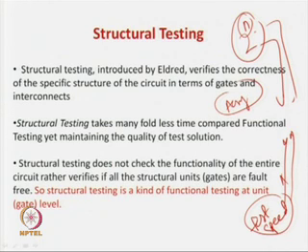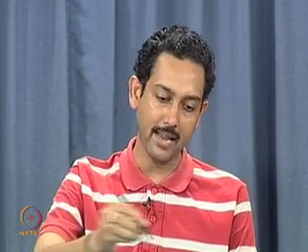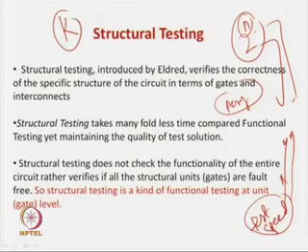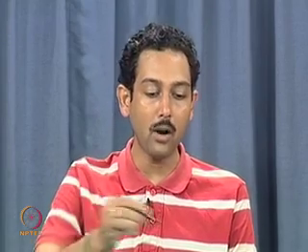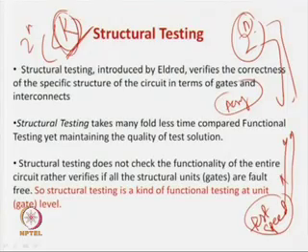But statistics, meaning statistical results or history, has a very important role in testing. So, in testing you apply a certain kind of test strategy, and then you see what the outcome is for around, say, 2 to 3 years in different manufacturing industries. For example, let us assume that somebody has found a technique in which you can apply only k patterns to test a circuit, where k is very much less than 2 to the power n. Then we keep using this number of test patterns and keep testing the circuit and doing the binning, that this is a normal circuit, this is a defective circuit, but we do not apply 2 to the power n, we apply only k test patterns.